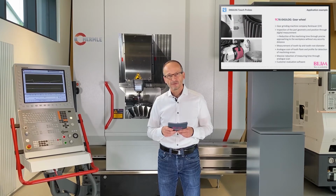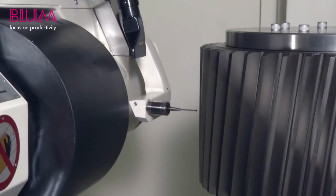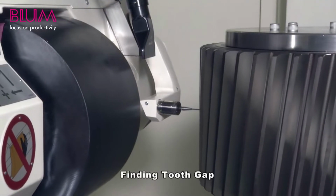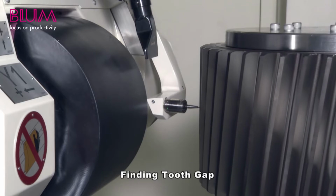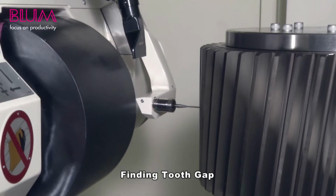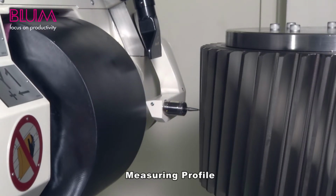That was a lot of theory. I'd now like to go into a little more practical detail and show you a few examples where DIGILOG probes have been integrated into production processes. The first video shows a hardwired TC76 DIGILOG, which is permanently installed on a continuous generating gear grinding machine. Its task was to precisely record the position of the blank before machining in order to reduce the grinding allowance to a minimum.